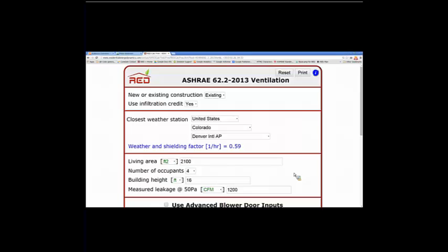It would be better to run it intermittently. Good question, and I can say with authority because this was an interpretation request 2 years ago, and the committee did decide that the entire volume of the house would have to be used in the 5 ACH calculation at that time.